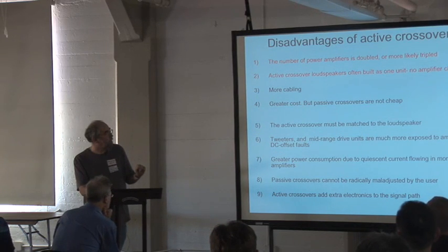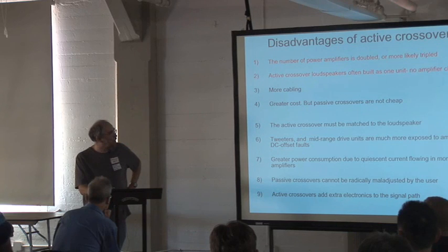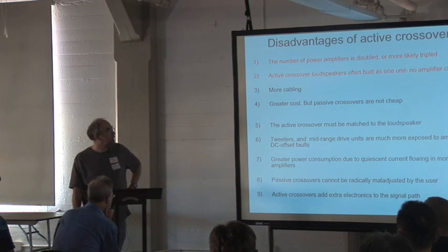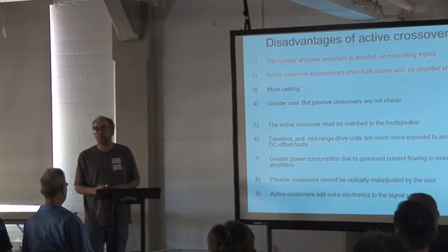One of the worst things that a power amplifier can do is to have a DC offset fault. Typically the output goes bang up to one of the rails, and that can be extremely destructive to loudspeakers, obviously. And I have never designed yet a DC coupled power amplifier which didn't have offset protection in the form of a relay that opens when things go wrong.